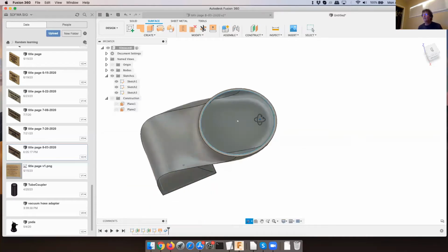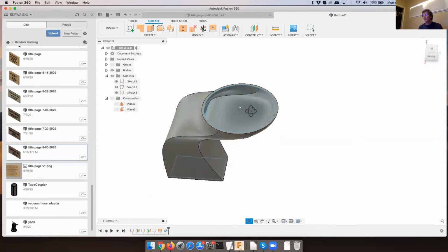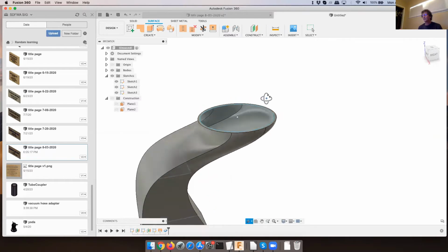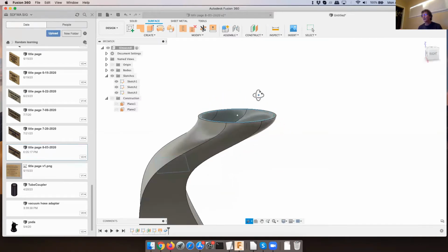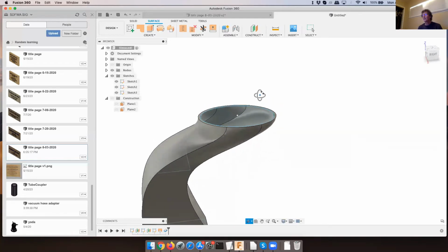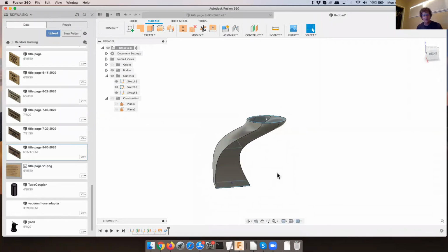This is effectively the same as making the solid one and doing a shell. So the obvious question is, when would you pick one? When would you pick the other? Surfaces, it depends on the kind of functionality and the follow-on features that you want to do. Because surfaces give you a little bit more freedom to do certain things in some regards, and solids are simpler.